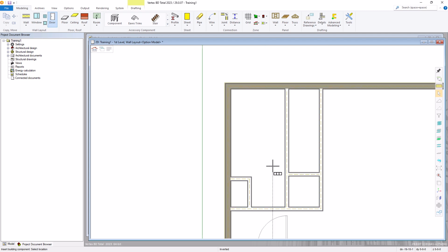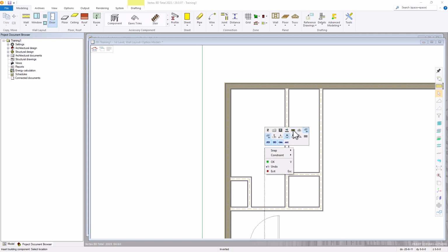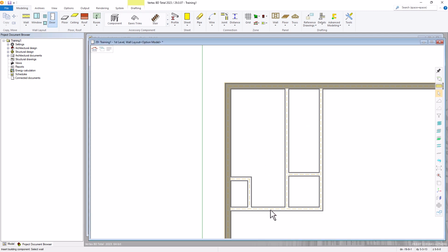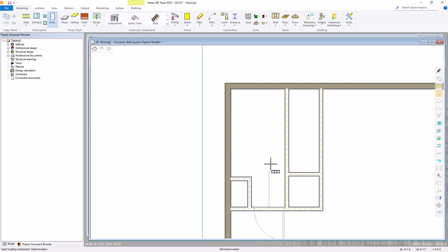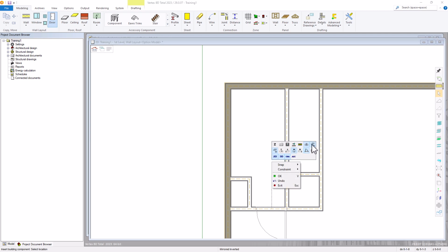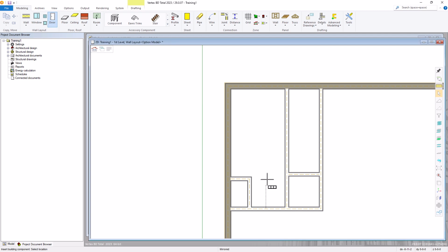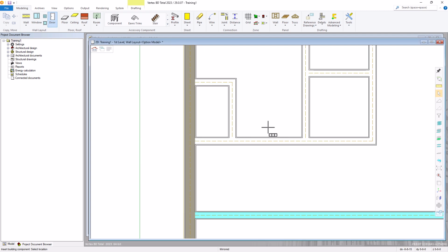Now let's go over in the bathroom area. I'm going to right click, select wall. We're going to select this horizontal wall here. Let's go ahead and add the bathroom door. That's also a 2.8, but we just need to change the hinge and flip that door. So we're going to right click, we're going to mirror it, and then we're going to right click again and flip it in 2D so that it's hinged over on the right. And we're going to find the midpoint. Get that yellow icon and click on that.